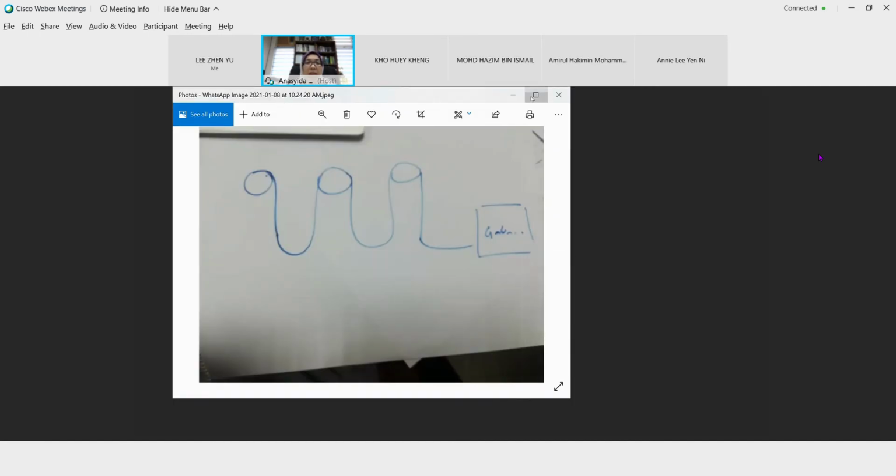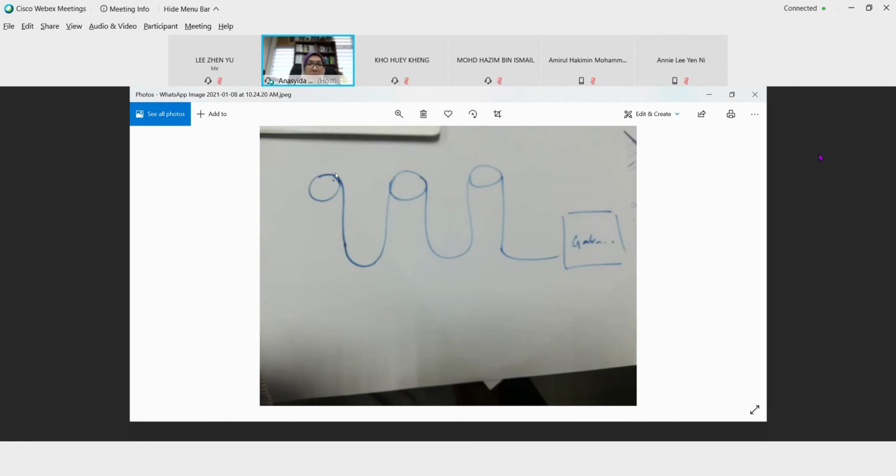Can you see? Okay, so this is the roller. I want to tell you that the strip is like a roller. This is the roller. I want to write. So this will be the annealing process here. So there will be an annealing process carried out before you do galvanizing. During annealing, the boron inside the steel might combine with oxygen to become boron oxide. So what happens here, the boron will stick to one of the rollers.